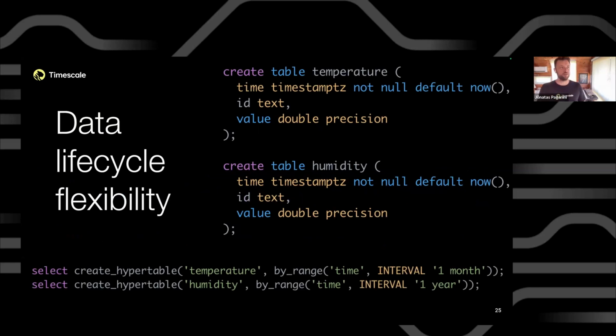Another alternative is when you think about your data having different life cycles. Let's say you are looking at temperature. Maybe you are building a system with both temperature and humidity, but your system is very focused on temperature, and humidity is just there. So you have a different data life cycle. Your data will be there for less time, or it will have a different density. I don't need humidity hour by hour, I can have it every 4 hours, but temperature I need every 30 seconds.